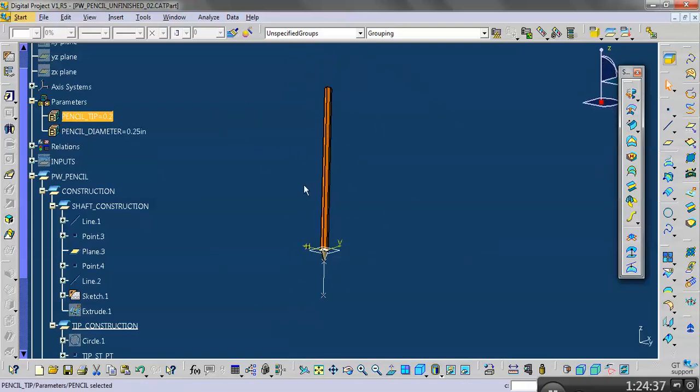If we wanted to replicate this pencil, it's very easy to create a power copy and instantiate it all over the place because it's a little parametric element. If you want to build a funky adaptive facade based on environmental inputs, you can create this tiny smart facade component and replicate it. If you've defined parameters clearly, like we have done, where we let our pencil make decisions, your smart component can make decisions based on environment, adapt and produce variation. Those little smart components are in this program called power copies. So you can make a little power copy and instantiate it all over your facade, and it could do different things based on its environment.